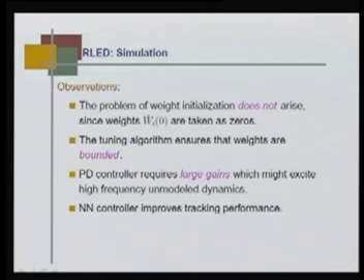So, observations: the problem of weight initialization does not arise since these are all taken 0. The tuning algorithm ensures the weights are bounded. The PD controller requires large gains which might excite high frequency unmodeled dynamics. The neural network based controller improves tracking performance.